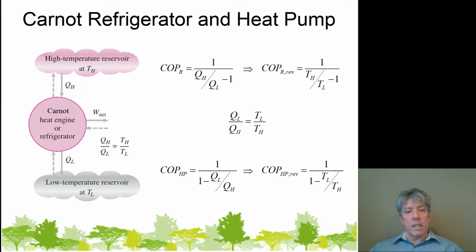So you can sacrifice a little bit of the thermodynamic theoretical efficiency and use, instead of a reciprocating compressor, something like what mine has, which is a Copeland scroll compressor, which is much more efficient. It doesn't have as much irreversibility inherent in its design, and so it just performs better. It doesn't require as much work to compress the refrigerant as a reciprocating compressor requires. And so it can afford to lose a little bit in generating higher temperature air, and of course they're using a different refrigerant and modern oils and things that again reduce irreversibilities of friction.